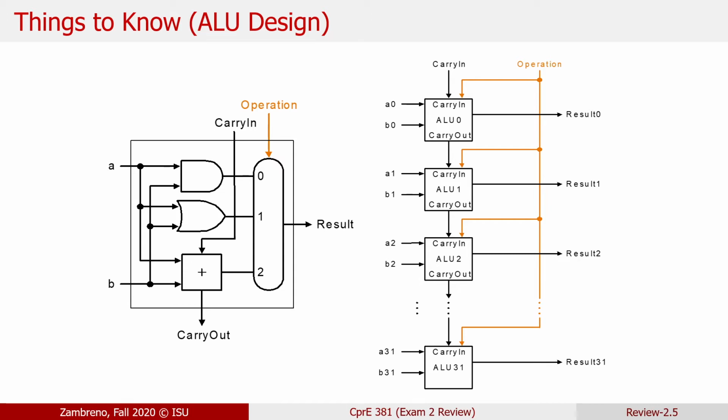We also looked at how we would potentially manipulate that ripple carry chain to support SIMD extension instructions that do some parallelism, like a byte parallel add instruction. And when we looked at the shifter, how we would potentially tweak things to support different operations as well. One of the practice exam questions talks about that issue.